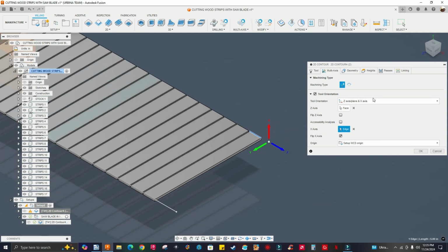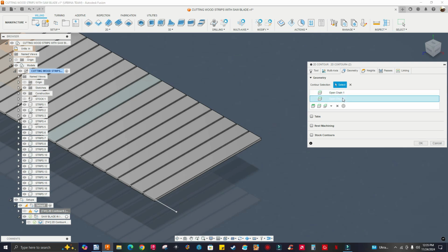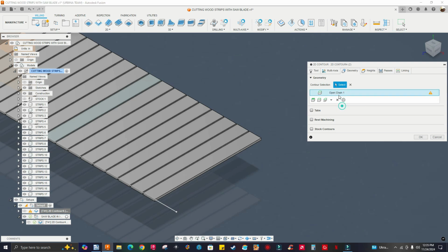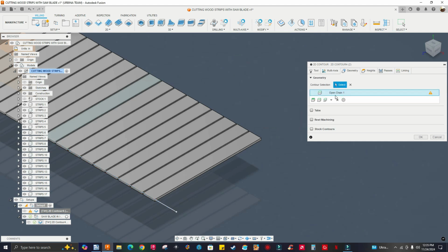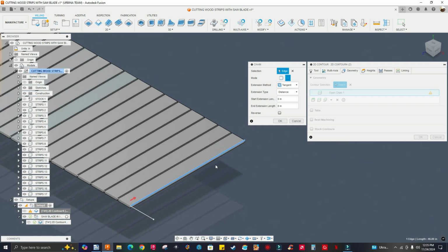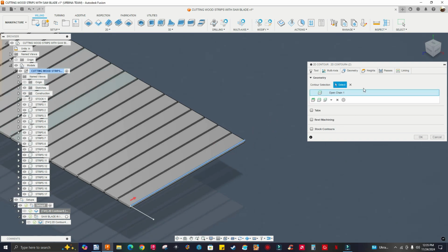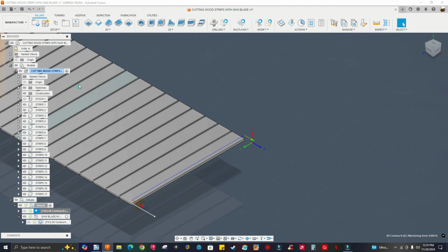Let me see what I get when I create toolpaths here. Let me click OK. Oh yeah, contours. Okay, so I don't need the second one. I only need one. Right click, edit. Select the first one. Right click, edit. Oops. Yeah, the second one I selected was right click, delete, not edit. Now I'm gonna select the first one. Right click, edit. Click on this X and select this edge. Click OK. Click OK. Right click. Oops, not post. Yeah, simulate. Okay.